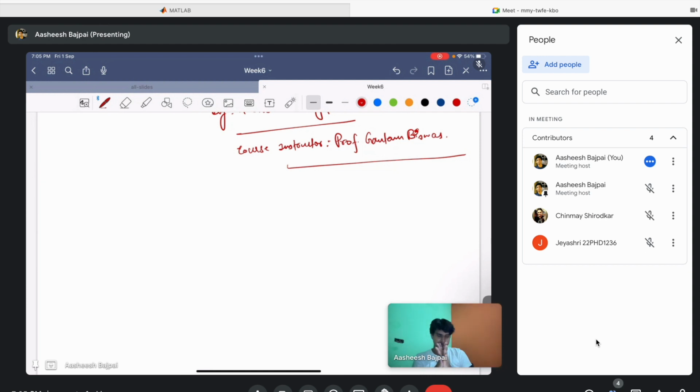Let me think. I think boundary conditions should not be directly a boundary condition here, according to me. If you are calculating heat flux, then it should be something like Neumann type of boundary conditions. Along with that, there is a specific